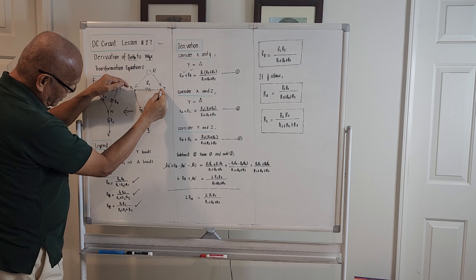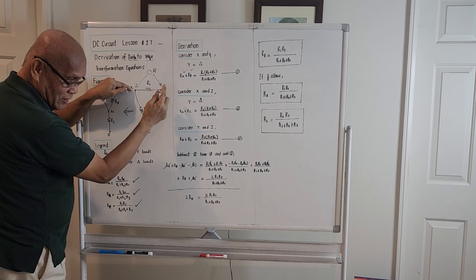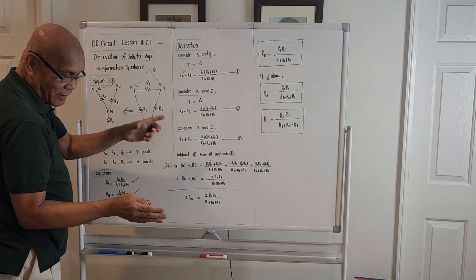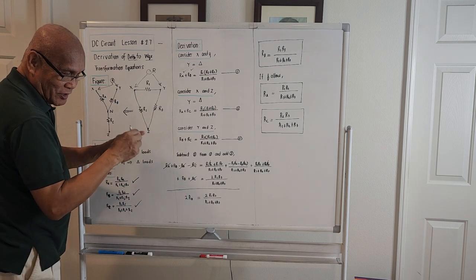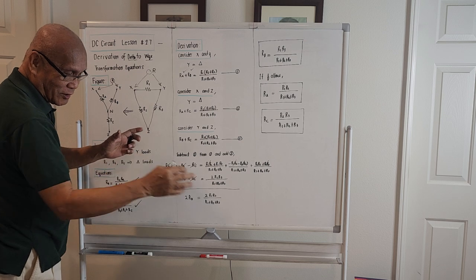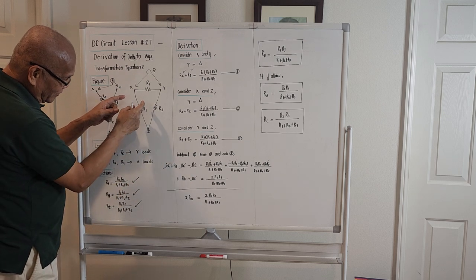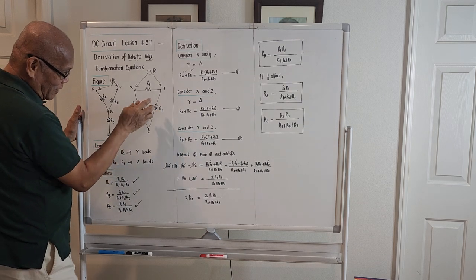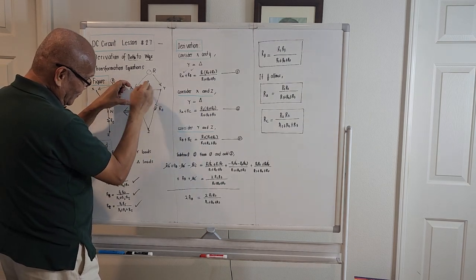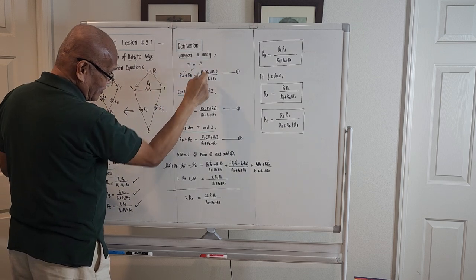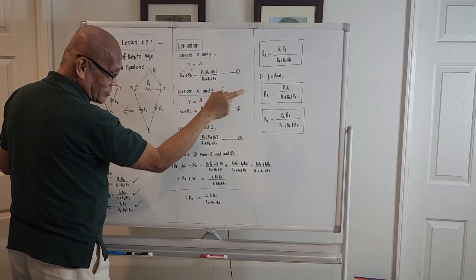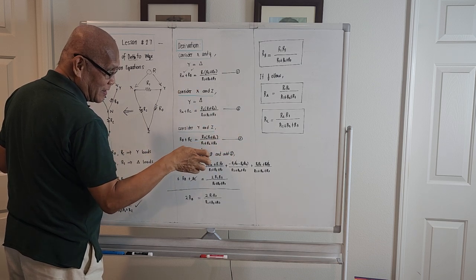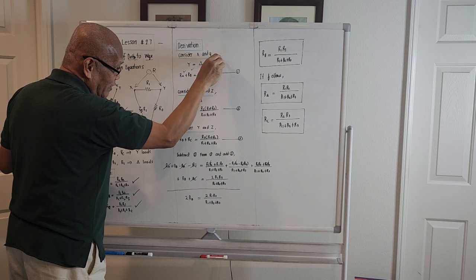So just in case we get the reading here, we know how to compute for the resistance of two branches which are in parallel. It should be the product of the resistances all over the summation of the two individual resistances. But the second resistance is actually the sum of R sub 3 and R sub 2.